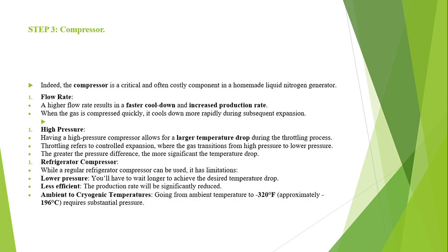Refrigerator compressor. While a regular refrigerator compressor can be used, it has limitations: lower pressure and less efficiency from ambient to cryogenic temperature. And you can see that I have mentioned here it will be minus 320 degrees Fahrenheit, or minus 196 degrees Celsius.